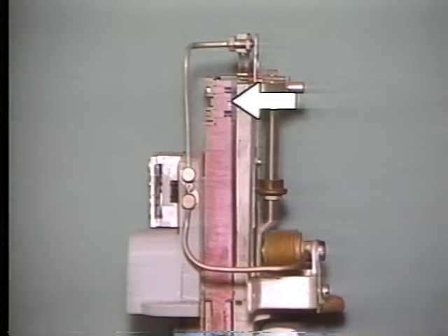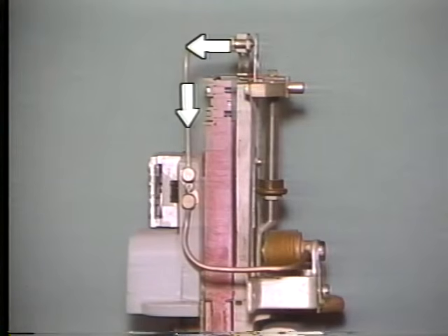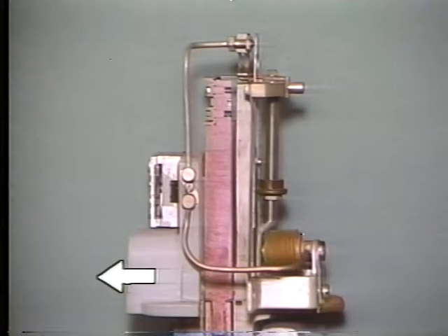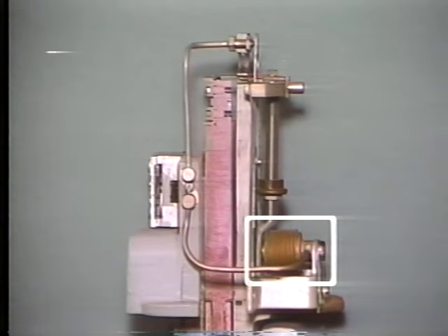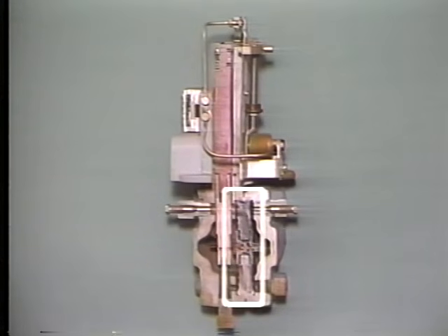The motion of this balance beam positions a flapper nozzle error detecting mechanism which changes the pressure in the nozzle back pressure compartment. This change in pressure operates a pneumatic relay. In turn, the relay, acting as an output mechanism, creates an output pressure. This pressure is sent to another instrument as well as to this balancing bellows, which is the balancing mechanism for this transmitter. The bellows expands or contracts to balance the differential pressure change to the diaphragm input mechanism and return the transmitter to a balanced state.